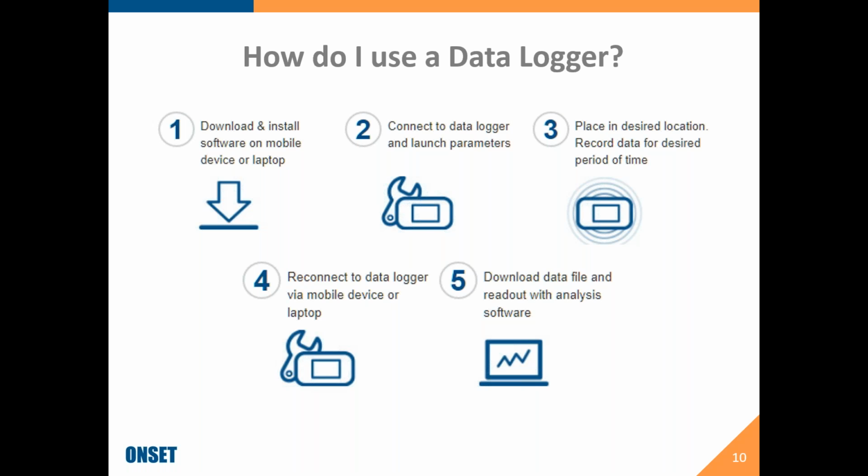How do you use a data logger? They are going to be connected to either software on your computer that would recognize the date and the time, or it could be on your mobile device. Now that we have Bluetooth data loggers, they're set up and read out on a free app to a mobile device. So you have control over this data logger: when it's going to start, how long it's going to run and record based on the interval you select.